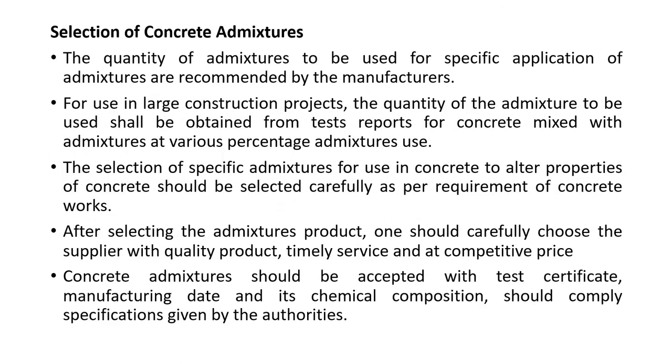Selection of concrete admixtures. The quantity of admixtures to be used for a specific application is recommended by the manufacturers. For use in large construction projects, the quantity of the admixtures to be used shall be obtained from test reports for concrete mixed with admixtures at various percentages. The selection of specific admixtures for use in concrete to alter properties of concrete should be made carefully as per the requirement of the concrete works.